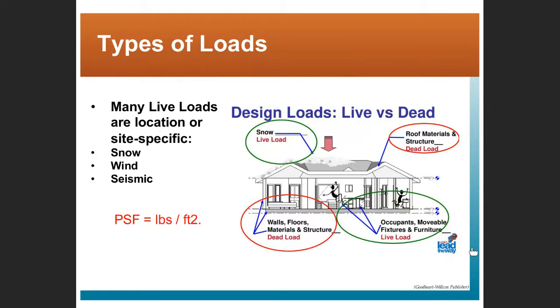I think in some of our drawings, we've seen the terms live load and dead load. It may have said something like, assume a dead load of 10 PSF. PSF is pounds per square foot. So dead load is the weight of the materials and the structure itself, and live load, in the case of inside the house or inside the building, is the occupants, the people, the furniture, the furnishings. Everything that's inside the house, that's live load.